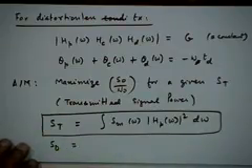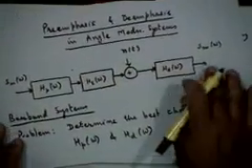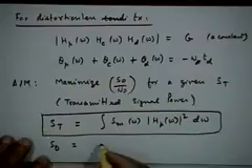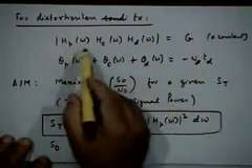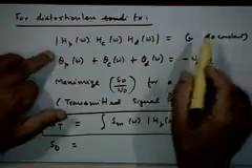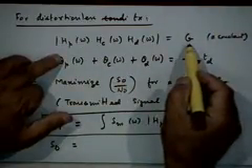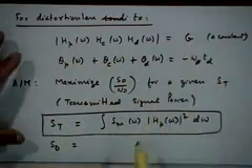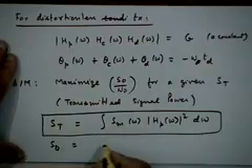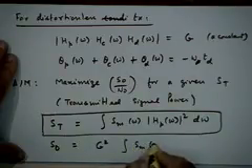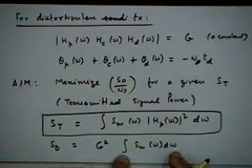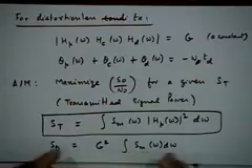What is output signal power? Final output is what? S_m(omega). So output signal power is simply, sorry, I made a statement that let there be no attenuation. Sorry, that's not correct. Attenuation is contained in this factor of G, right? Attenuation or gain or whatever you like to call it. So output signal power would be G squared times, tell me, integral of S_m(omega), right. This is the final signal you are getting, this is the attenuation factor.